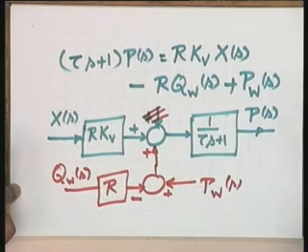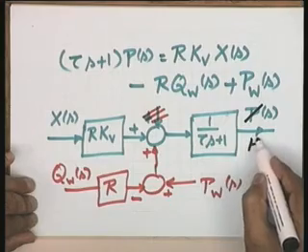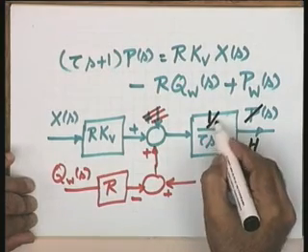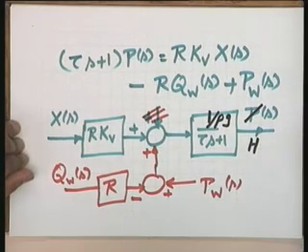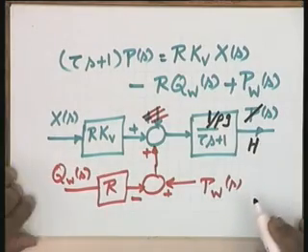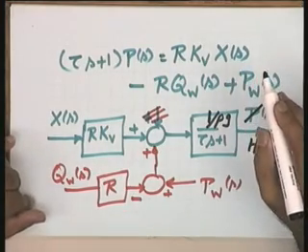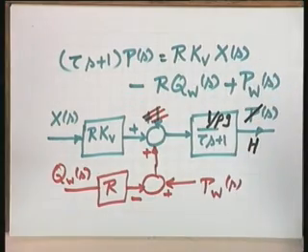Well, here itself I can make a change. If I make this P to the variable h, the net effect will be this 1 will become 1 over rho g. It is possible to write this as 1 over rho g if your controlled variable is h. So, this becomes the total mathematical model of the system, which we will be taking in our control system applications, where the plant models for the liquid level systems will be required. I conclude with the statement that the plant models will most of the times turn out to be first order models.